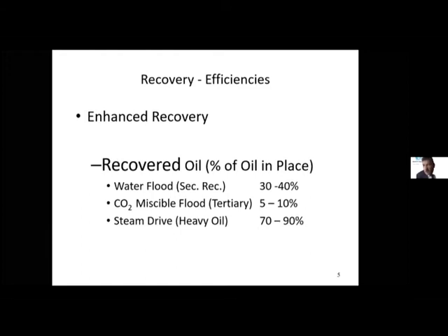Why immobile? Because I lost the energy in the reservoir. I mean, I lost the pressure of the reservoir. The reservoir has no more pressure inside it to push the oil up. So I build up the pressure by water injection or gas injection. Or the oil is very sticky, adhesive oil. It sticks to the rocks itself, so I need to take it out of the rocks, as if I am washing the rocks. So I use chemicals in this case. We call it sweeping efficiency. So that is the answer to why we use it.